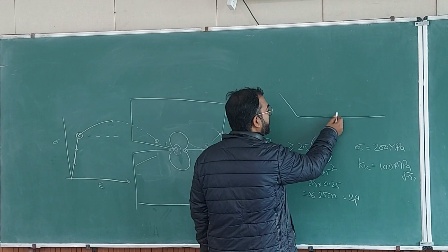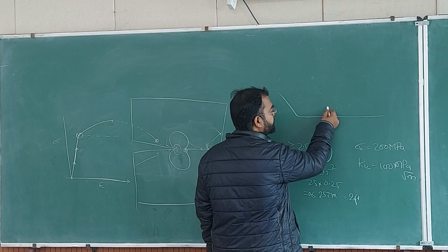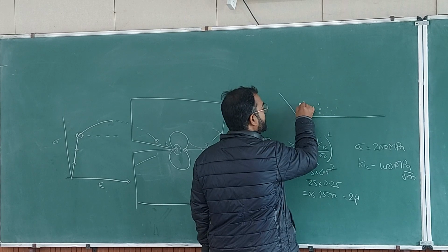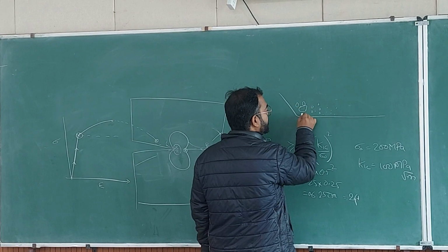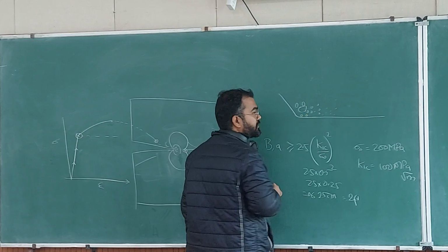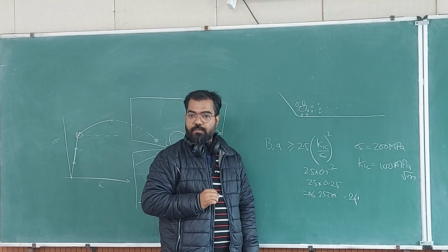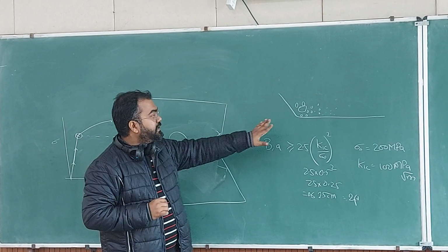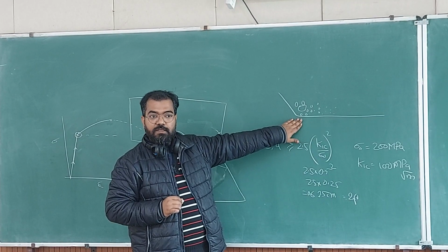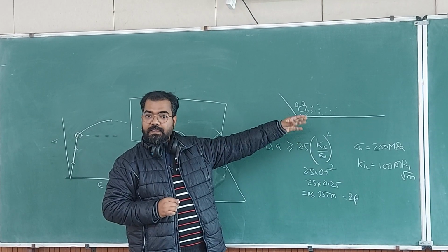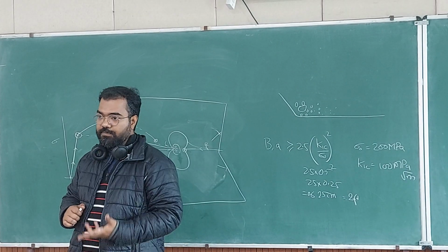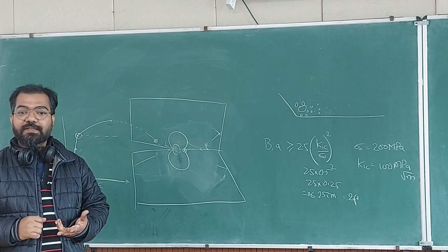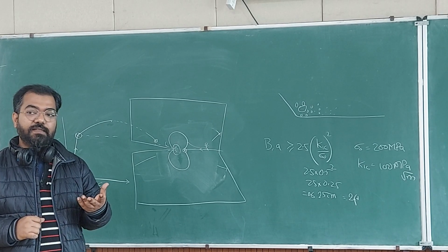So somewhere close to the crack tip you will start seeing voids, and then you will see bigger voids and smaller voids. Then you will see even bigger voids and coalesced voids and smaller voids. Okay, so you are progressing in damage also. So in this region where you have a lot of damage, plasticity is also not holding, and then there is a zone where we don't really know what is happening. Okay, some people don't like this analogy, but still I want to give it: it is like a black hole.